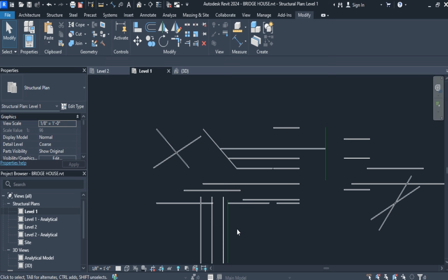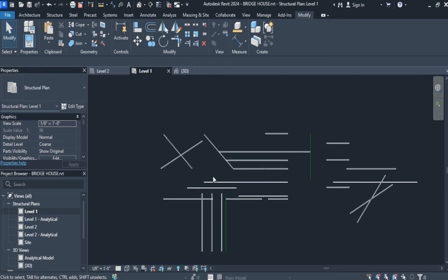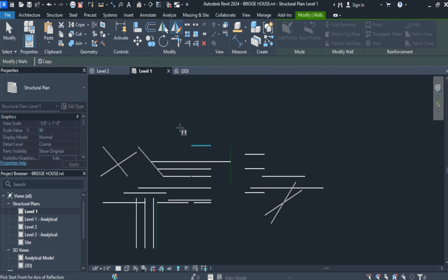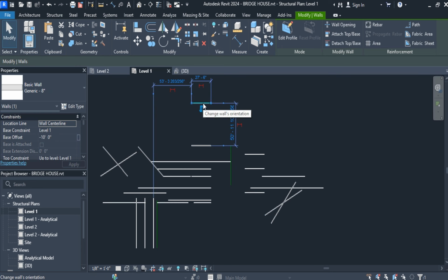Then the next is the mirror draw axis tool or command, which has a shortcut of DM. It draws the axis. You draw the axis you want to use as your mirror using the left click on your mouse. You can still change the options bar to your desired setting. In this case, we can choose this wall mirror, so we can use our left click on the mouse, draw a mirror, and our element has been mirrored to that side.